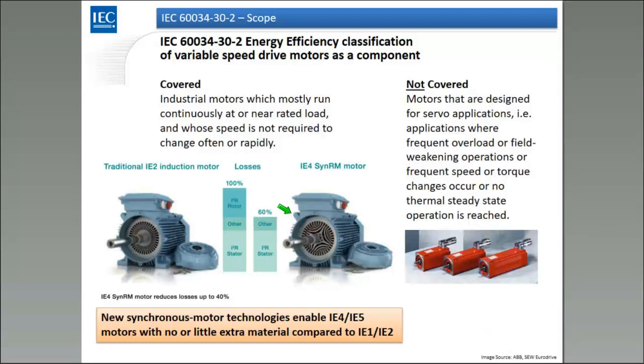These motors are now available from several suppliers. ABB is just one example. You've got to ask them about the price, but I wouldn't see any reason why these should be significantly more expensive than those. Actually, they should be a little bit cheaper. You will need a frequency converter to operate this motor. That's the drawback. You will need a frequency converter.